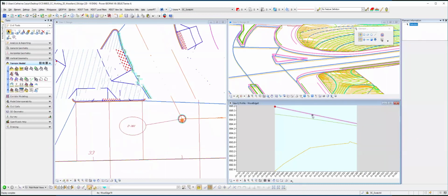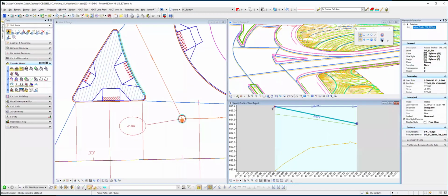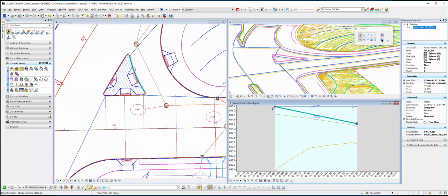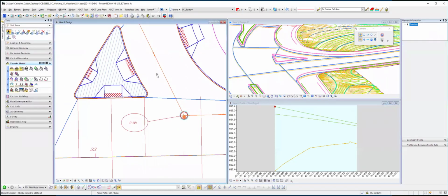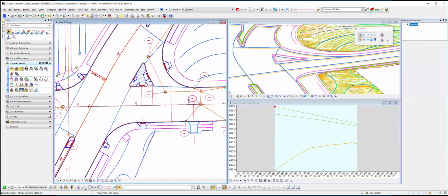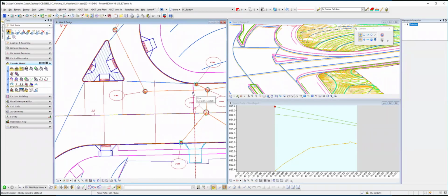Here's this one. It's coming down. I had to be exactly, this was quite challenging. I had 2% from this edge downward to connect to this pavement down here. So I scratched my head at this one for a while, but as far as a warping perspective, I used, again, some common sense, some practical experience from being in the field building, as well as the actual calculations, super elevation, transitions, and things of that nature to determine what was going to be acceptable from a transition standpoint. And then this pavement edge warps considerably.